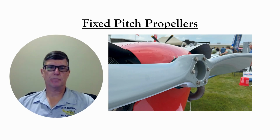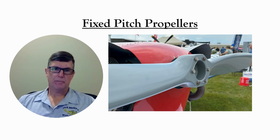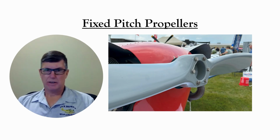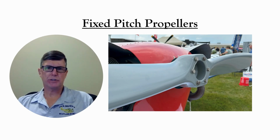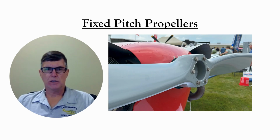For maximum cruise performance, on the other hand, a steep pitch is best, meaning a high pitch number. However, a cruise propeller will resist rotation at slow speed, and it'll prevent the engine from turning as fast as the engine needs to in order to generate high power. So a blade pitch that's a compromise is typically what is chosen.